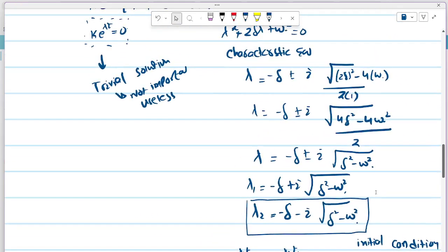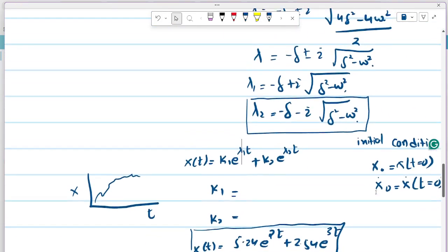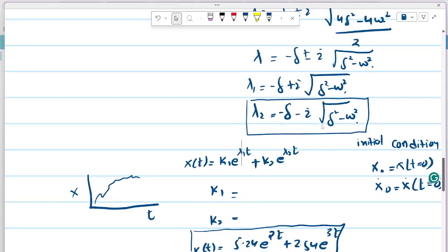So in this case, we will look into how we can utilize these roots and try to understand the effects of different values of roots on the physical interpretation of our system, to find out whether I have designed a too heavily damped system, or my system is very lightly damped. Should I increase the damping? Because the mass is not easily in our control, and the spring constant is not in our control most of the time. What we can control is how much damping we can add or remove. That's why we analyze the system based on the amount of damping.